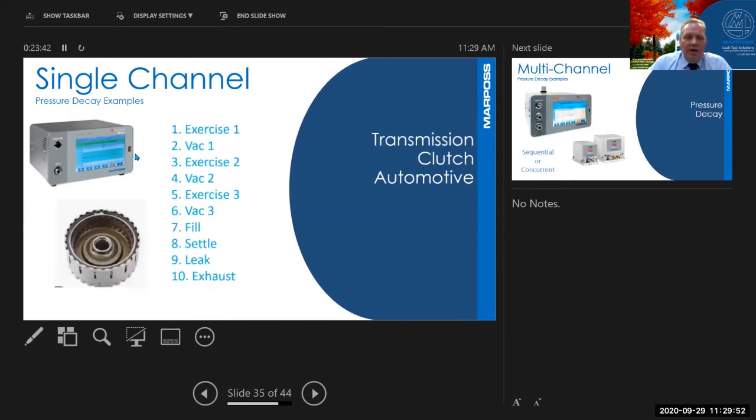One of the other things we start seeing with single channel testers is exercising. On automotive clutches, a lot of times what they're trying to do is there's a seal in there that we exercise a little bit up and down and get it to move to seat in the correct location. So what you'll see normally is 1 to 4 exercises where you turn on and pressurize it with 10 PSI, pull a vacuum on it to return it, pressurize it, return it, pressurize it, return it, then go into a normal leak test. This is rather common when testing automotive clutches.